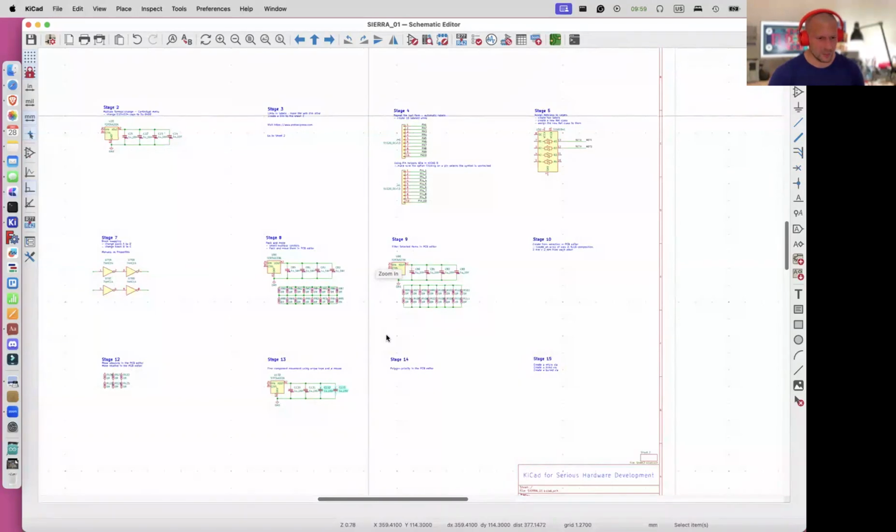Chet Seaver asked, what is the difference between length tuning of differential pairs in 7 and 8? Yeah, the length tuning in version 7 was that you set the target length for all the tuning process. For instance, you set 50 millimeters as a target length, and then once you tune the length of all the differential pairs you were touching, the target length was the set 50 millimeters.